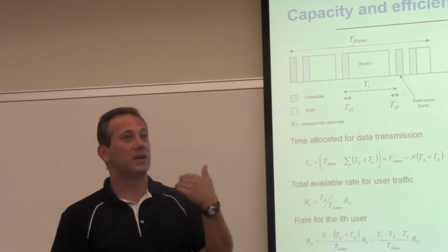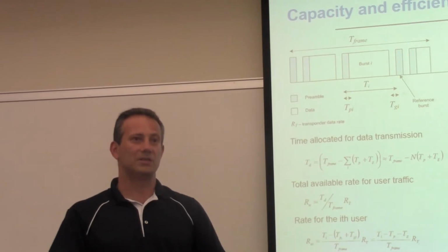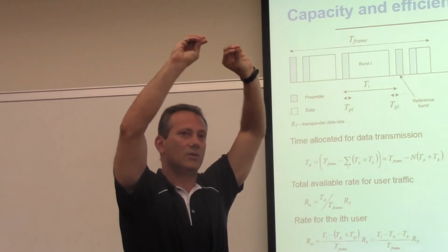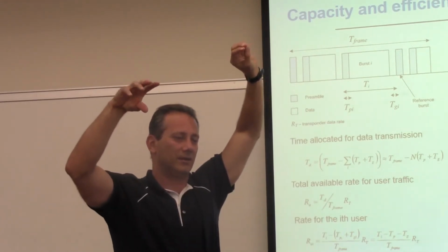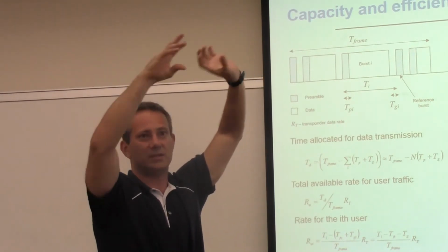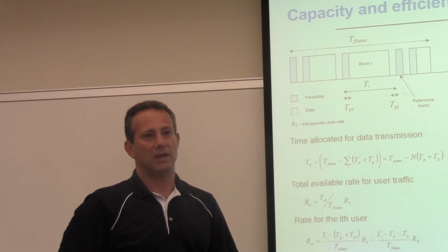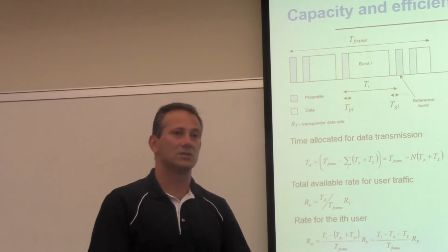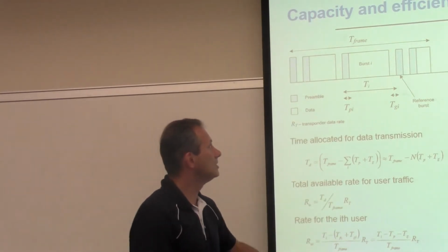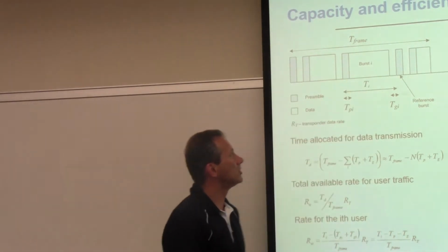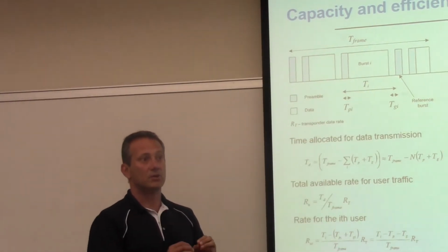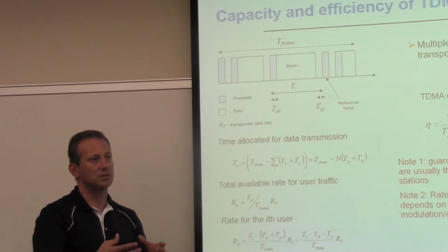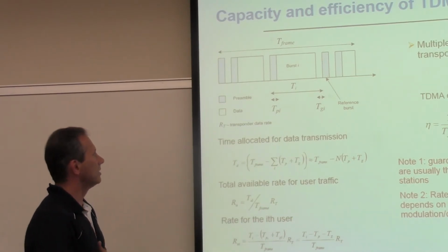Yeah, not only that, they come from different places on the ground. They all meet at the transponder, but even though you may make an attempt to synchronize them on the ground, by the time they reach the transponder, they're completely random relative to their phase and even their frequency, because there's a drift among different earth stations. There may be Doppler shift. So there are many reasons why you have to have this burst containing its own preamble, because that preamble traveled the same path as the data. Therefore, it contains all the information that you need to sync to demodulate the data itself.